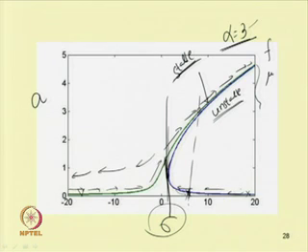In this bistable zone one can find two stable positions and one can have a jump up phenomenon at this position, and one can plot the basin of attraction to know to which state the system response will go, and find for what initial conditions the system's response will be this trivial state, or for what value the system response will be the non-trivial state. So, by taking different system parameters, in this way one can find the response of the system.